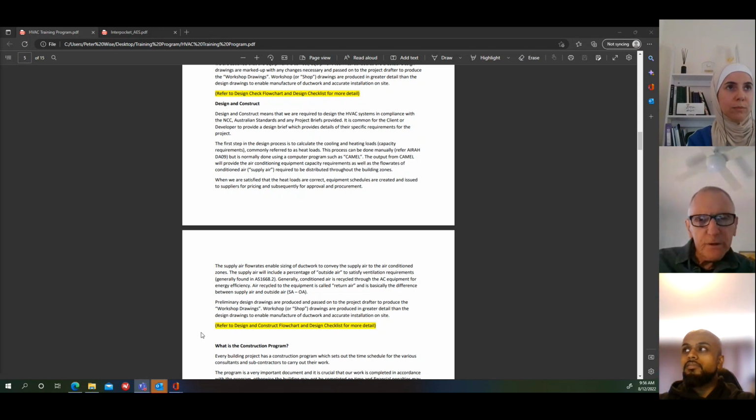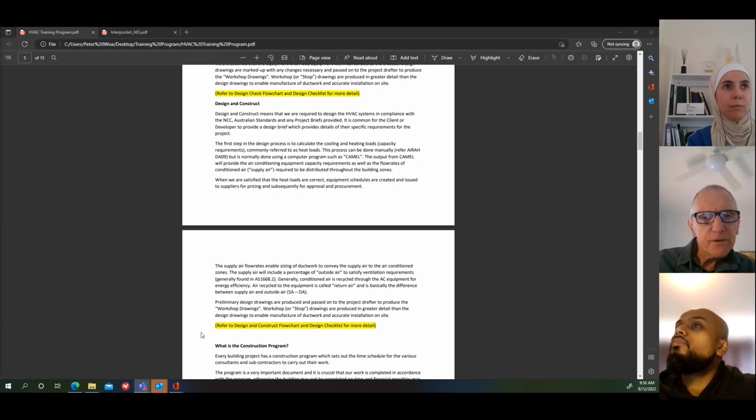So we've got to the stage where we've got a layout now, whether it's Bluebeam or Revit. Now Revit also will probably calculate the static pressure, won't it? So there's another benefit there, that you don't have to go through that process of calculating the fan statics. But as it stands at the moment, with your sketch, you can do a fan static calculation.